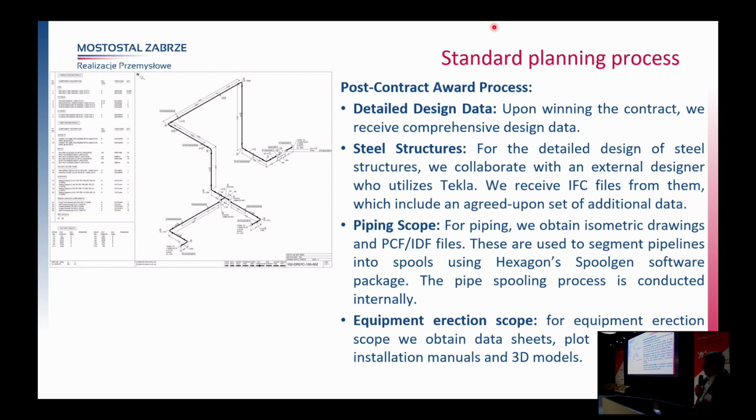For piping scope, this is really complicated because there is lots of data. A project can have like 2,000 pipelines. Each has to be verified, divided into spools. That's why we are using Spoolgen for that, and we are receiving from our clients PCF or IDF files, which is standard in the business for piping scope.